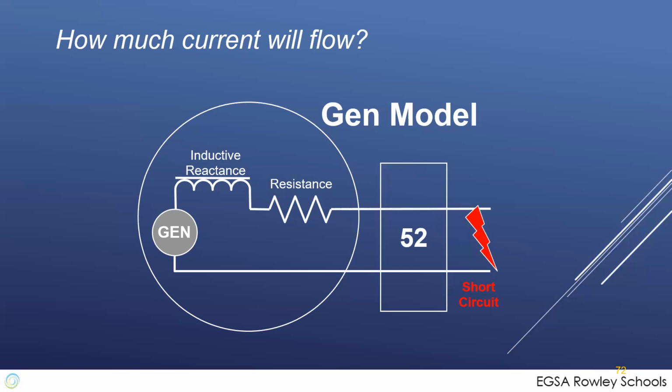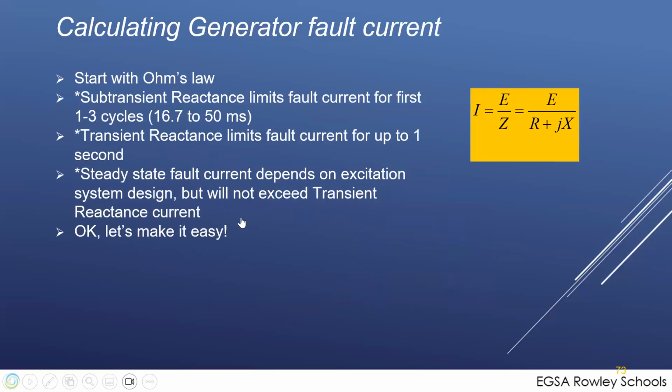We have lots of turns we've laid into the stator to accomplish this voltage we want to generate. There's 277 turns. We need to generate this much voltage. Anytime you have wires turned around steel, you're going to have an inductance. So it's possible to calculate this. It's a rather complex calculation that has to be done, and it also varies at different times depending upon how the field collapses and how the regulator kicks in and reacts to it. But it's a long, complicated equation, but we can make it easy. Let's make it easy.